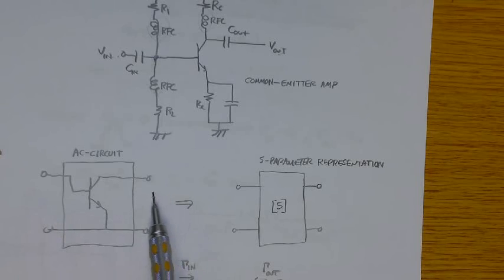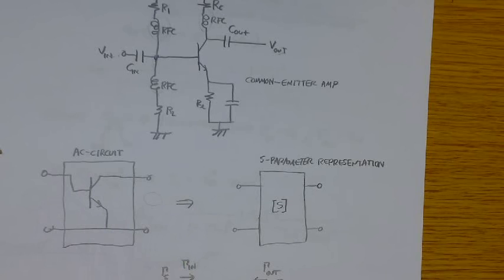Here's our input port, here's our output port, and so this is a two-port device, and from a microwave standpoint, we're going to represent that with a 2x2 scattering matrix: S11 reflection coefficient here, S22 reflection coefficient looking back into the output, S21, remember how the subscripts go. 2-1 is input on 1, output on 2. That'll be the forward gain essentially of the amplifier.